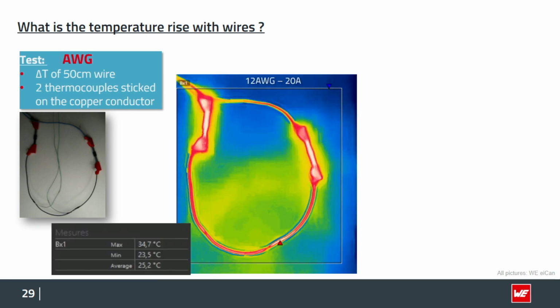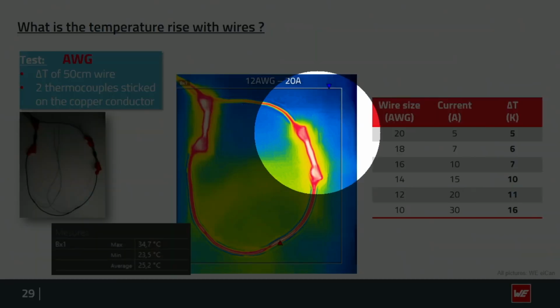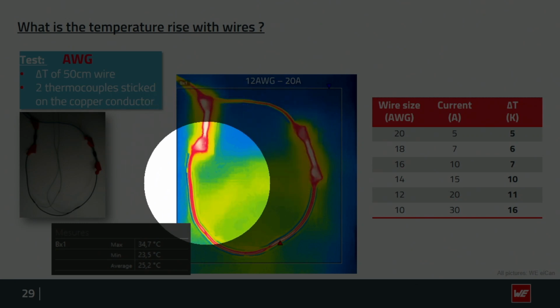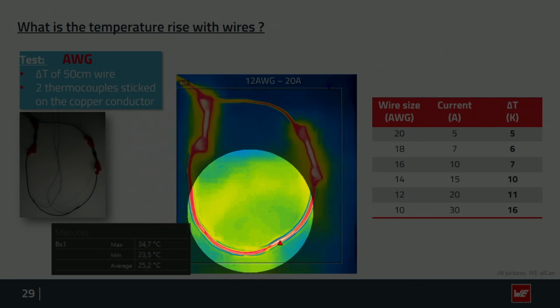Then, of course, we looked at it with a thermal camera again, which is the most convenient way to understand this. The thermocouples themselves give an exact temperature of the spot, and they are more accurate than the thermal camera, of course. But here we see the whole image, and we see that the highest temperature is on the whitest spot, which is inside of the connector. Now we're looking at the cable, which is red everywhere.